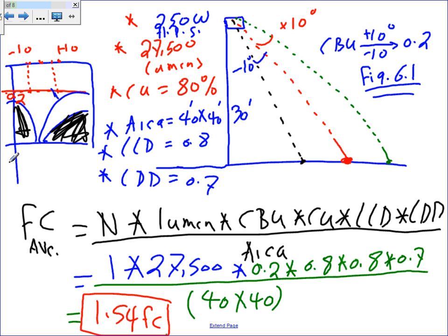Where is that indicated in the graph? It says mounting height of 15 feet, right above the graph. You just take your eyes and go up, you'll see ISO foot candle distribution, you'll see mounting height. 15 feet. Now I threw the 30 here, but if you change the height, you change the 30, it will give you different results. You're absolutely right.